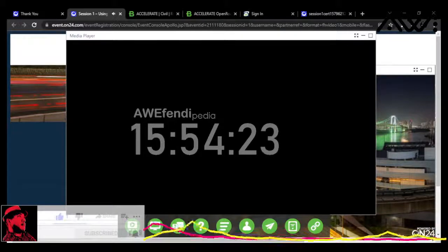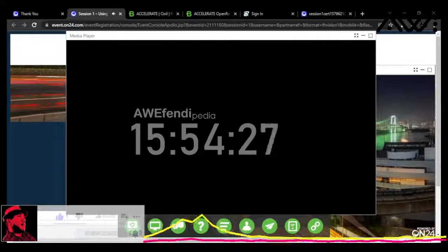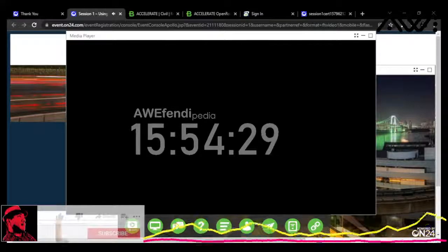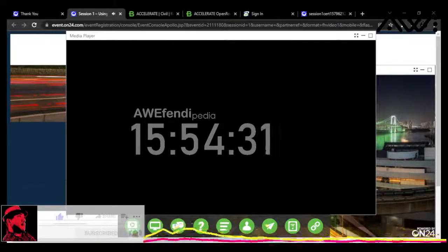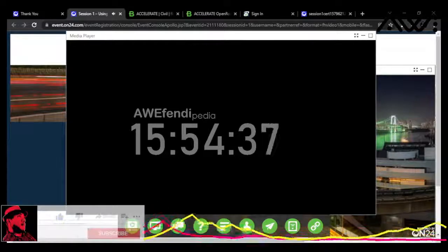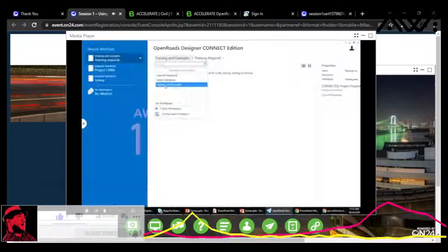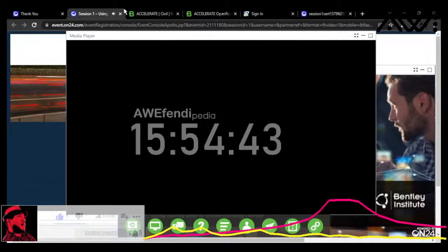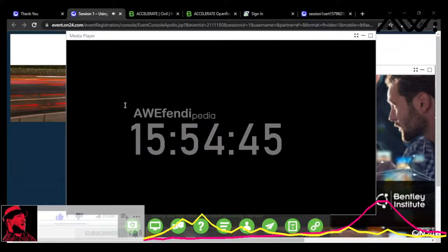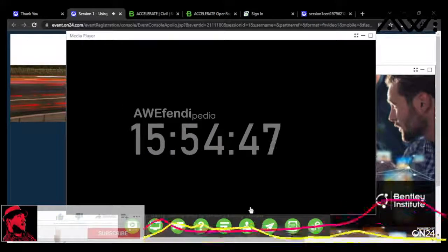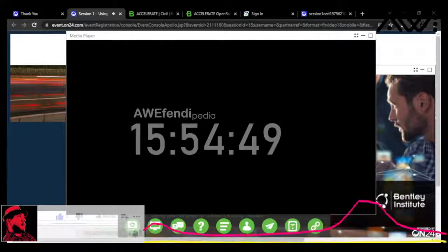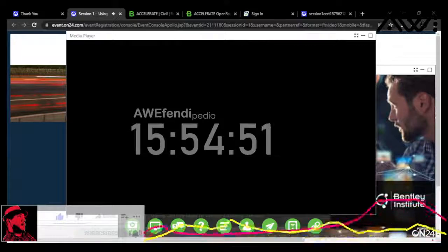This file is simply a comma separated point name, northing, easting, elevation, and then we have a feature code that describes the point. I'll note that there is a dash before the description, so that's something I'll need to set up in settings, and then we have the description here. Looking at my raw data, it looks like I'm using alpha codes for my feature codes, and a dash for my note or description, and that's it for our control file.